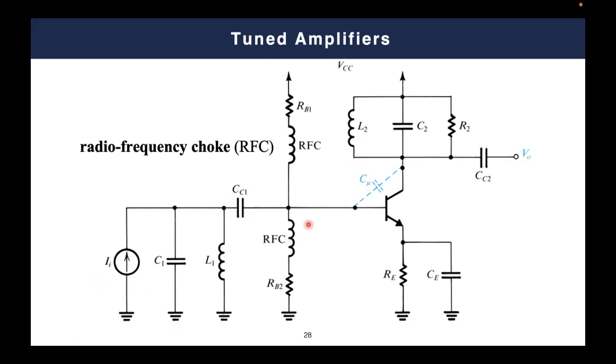So, for example, when I calculate the voltage here, I say that this voltage equals VDD times RB2 over RB2 plus RB1, which means that I assume there is no effect of this input signal on the DC biasing of this point. This is simply due to the bypassing capacitor. These bypassing capacitors are designed in terms of a capacitance value so that they show an infinite impedance in DC analysis, and this is simply due to the 1 over j omega C. So when you have omega equals 0, the equivalent is infinity.